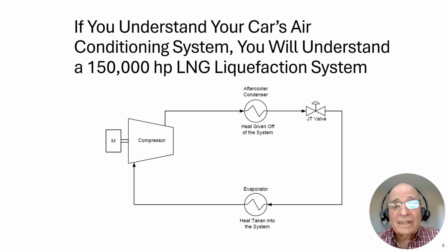In the case of your car air conditioner, using R134A, and that is sent to a radiator that is right in front. It's the frontmost radiator under your hood, and that is called a condenser. Now, what's actually happening here in this radiator is that this hot vapor, maybe it's about 200 degrees Fahrenheit, goes into this condenser, and it cools down, and then it condenses into a liquid.